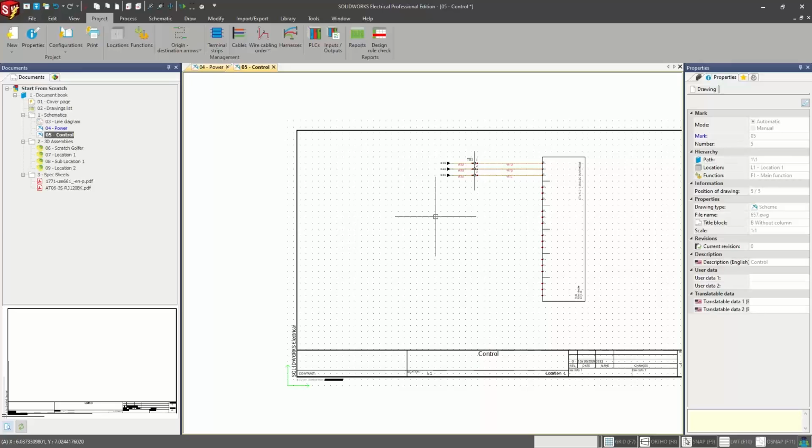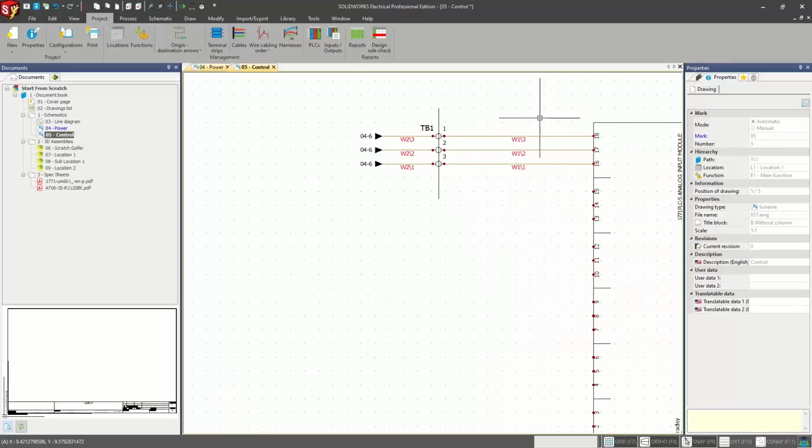So in the case of that, I drew all my wires out and then I'm using my air quotes, you can't see me, but I administratively turned those 8 wires into a cable in the same way I just did these by simply highlighting them and administratively turning them into a cable. If I disassociate these, they will be wires again. But right now the software is recognizing these as cables.